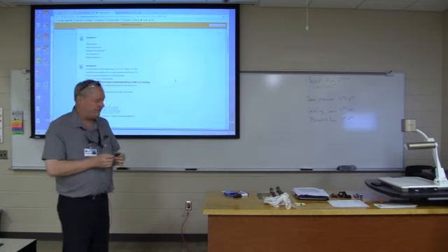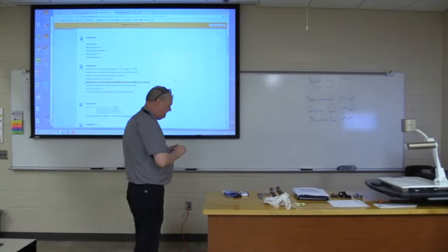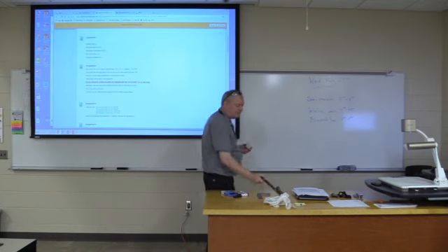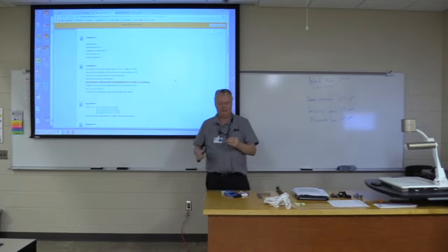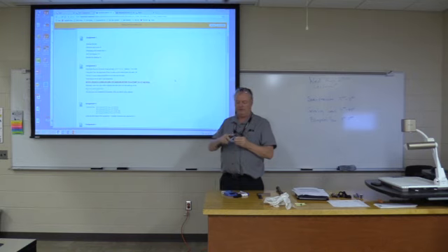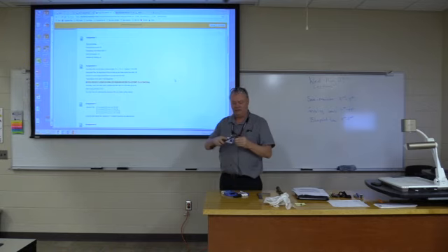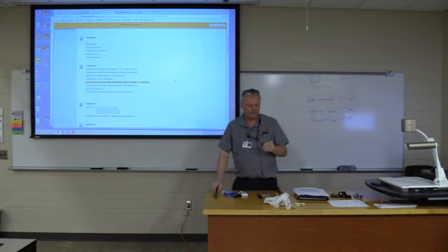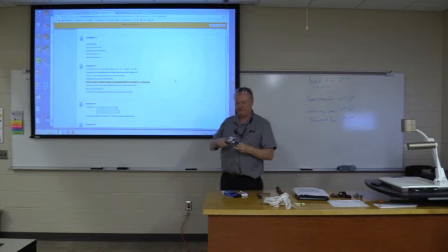And the way you do that is you get yourself a nice file. You put it in a vise typically, because sometimes the burr is pretty big. But what you're going to be doing is using the file, and you're going to just knock off the burr on all edges. This one has a really big burr, so it would actually be more appropriate to have this in a vise, but I'll just do it by hand as we stand here.